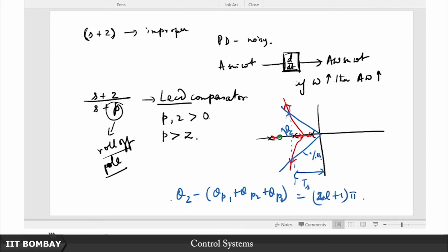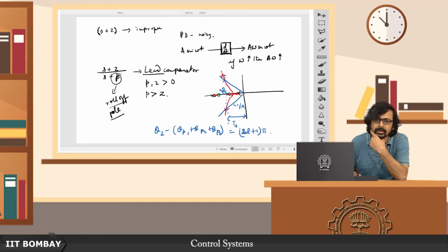So this theta z served to shift this root locus to the left. Yeah, because the uncompensated system was going out somewhere in this fashion, remember? So the moment we introduce this PD block here, this proportional derivative block, it allowed us to place the closed loop pole at a point such as this.